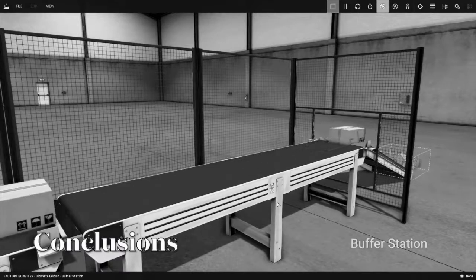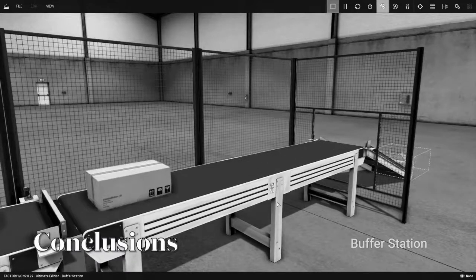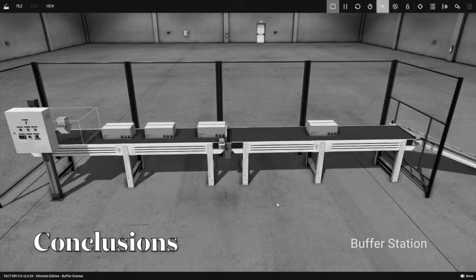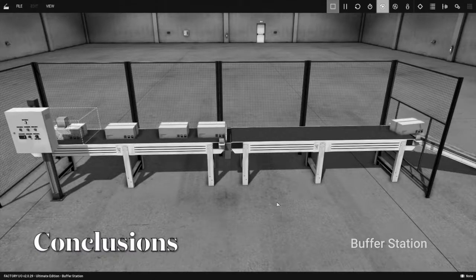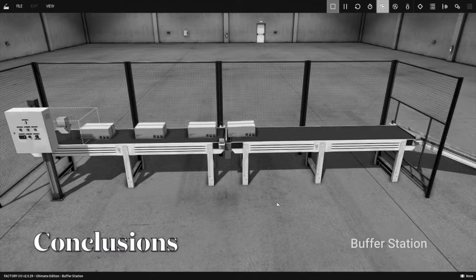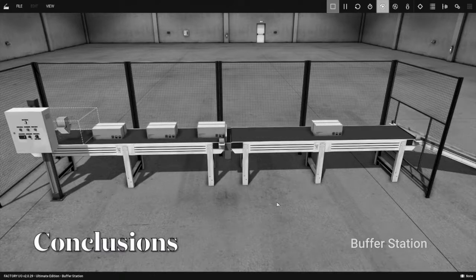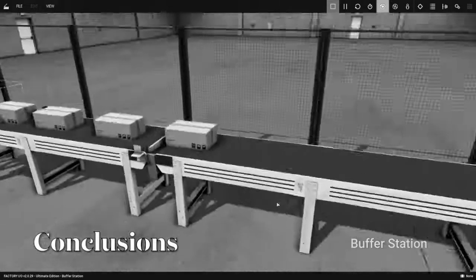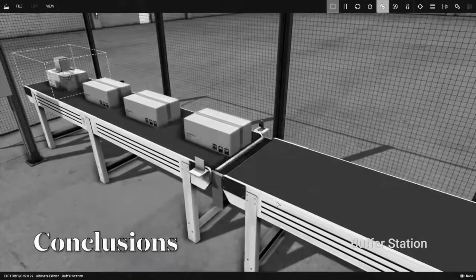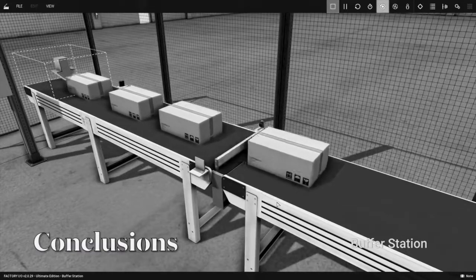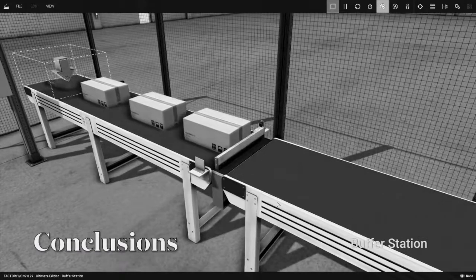among others. In this first challenge, we integrate several concepts learned in class, such as connection and configuration of a PLC and its components, connection to a digital twin through OPC communication, handling of ladder programming such as open and closed contacts, interlocking circuits, coils, counters, among others. And we managed to integrate everything in a small project to demonstrate its operation.